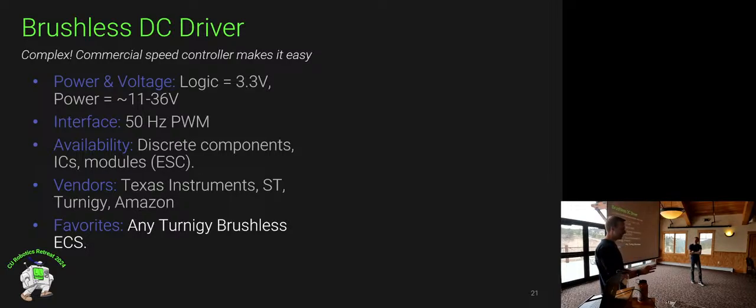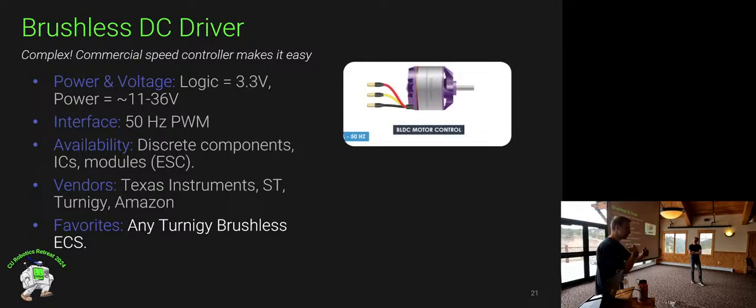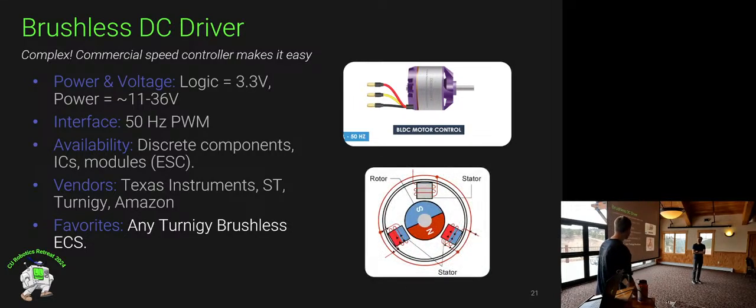This is where it gets complicated. And we're not going to spend a ton of time on this, but brushless motors don't have brushes. So you have to actively change the current signals that you're driving into these motors in real time to get them to spin. So unfortunately, there are now three terminals instead of two. And what that means is you have to create these complicated time-varying waveforms that basically turn on electromagnets inside of this to get it to spin at various speeds. We're not going to talk about that. And if you look at this diagram, it's like, wow, it's kind of complicated. Like I have to turn on this coil and this coil, but then I have to turn on this coil.